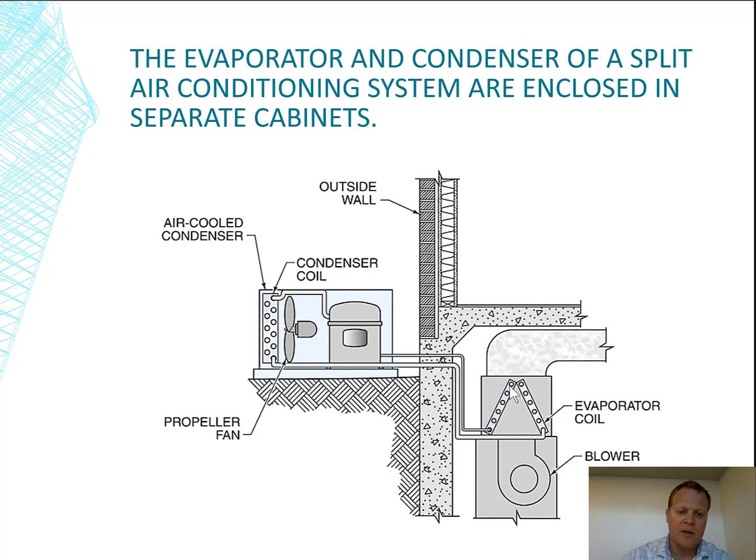This line should probably be up here somewhere, but it doesn't matter because this is still schematic in nature. And so this coil right here, the refrigerant is cooling off the air because it's trying to change from liquid to a gas, and it's cooler as it goes back into gas form and back into the compressor to be compressed again into high pressure gas,